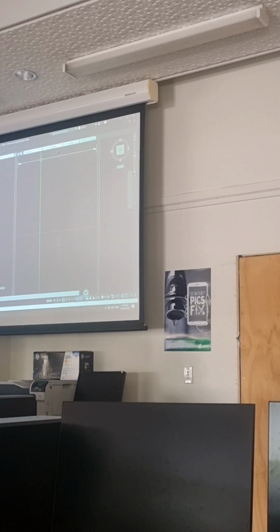P-edit, this time I'm just going to do the global width. Comes out the same. Width, I don't even know how big this bar is. How big is it? 12, is it? P-edit. Width W12, enter. Alright. Now, that bar bends down. No, sorry, it comes up towards us, doesn't it? Comes up, well, when you're looking on top, it's going down, and then it curves.